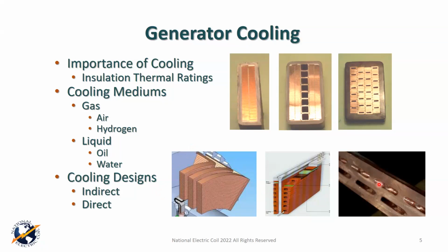Now, these two that you see to the right are a little specialized. This is a type that we say of a radial cooled, but it's actually a diagonal cooled. And GE was one of the ones that uses this most prevalent. And instead of holes vertically up through the conductors, these are at an angle.